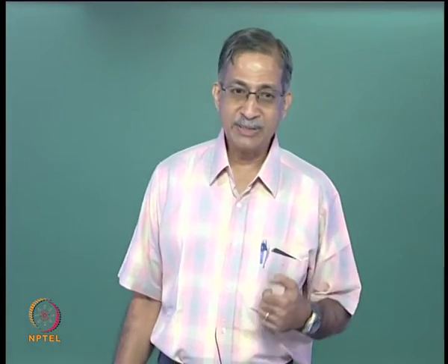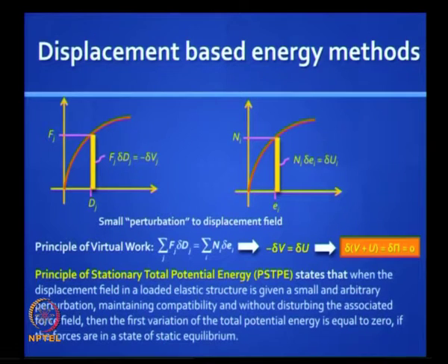So the principle of stationary total potential energy, PSTPE, states that when the displacement field in a loaded elastic structure is given a small and arbitrary perturbation, maintaining compatibility and without disturbing the associated force field, then the first variation delta pi, first variation of the total potential energy is equal to 0 if the forces are in a state of static equilibrium.